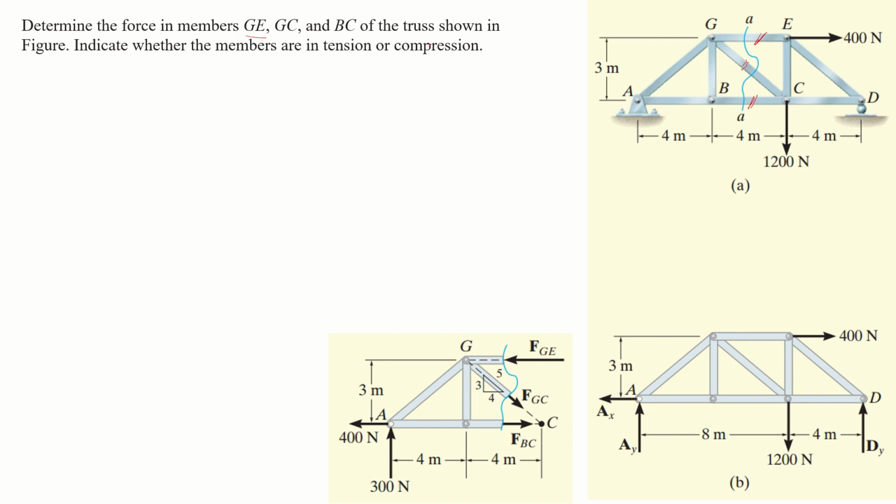So the first step is to decide where to cut this truss. If we cut this truss like this blue line which is already provided, all three members can be cut, and we can find the forces in all three members.